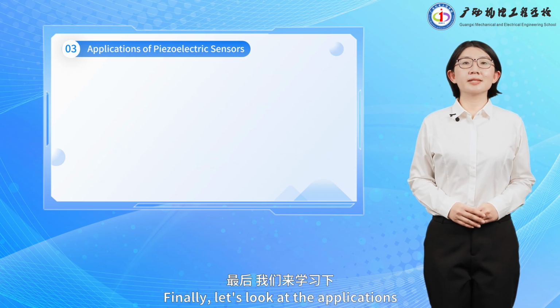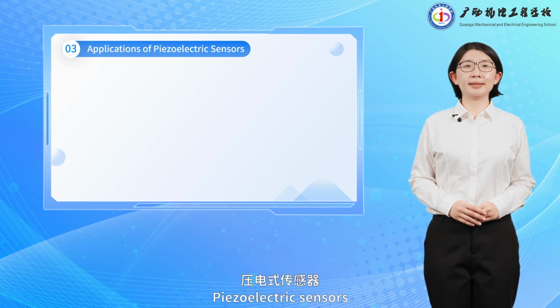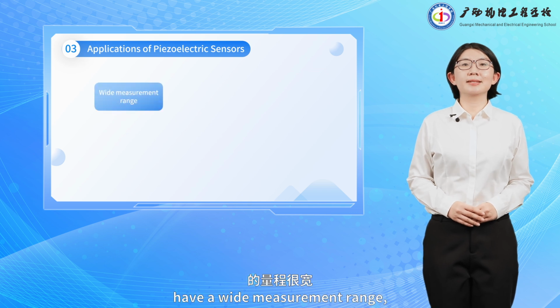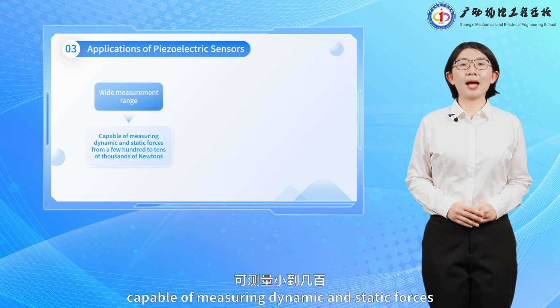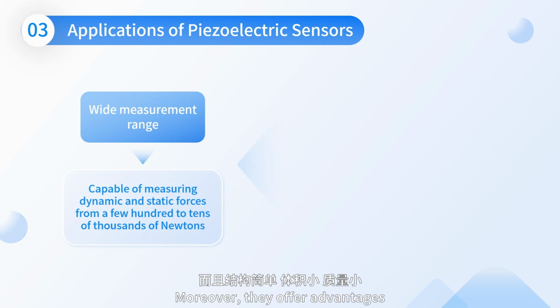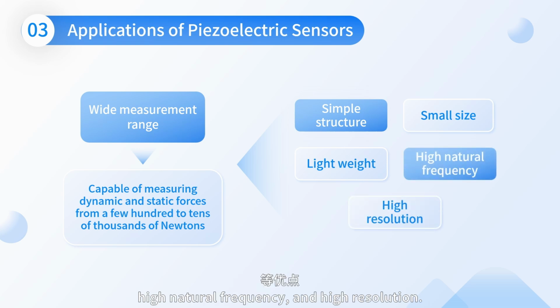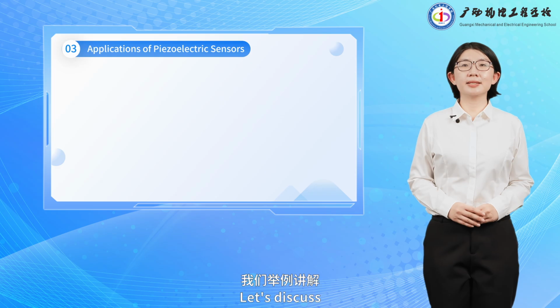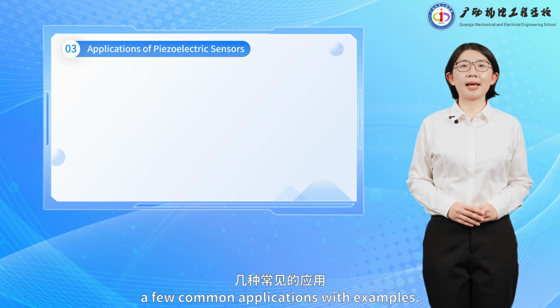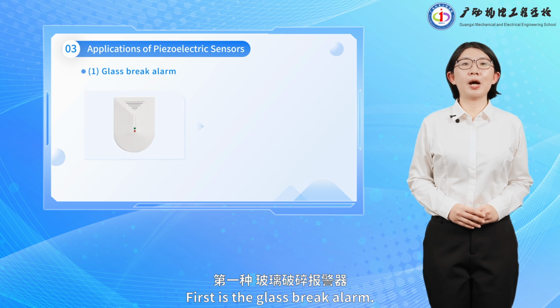Finally, let's look at the applications of piezoelectric sensors. Piezoelectric sensors have a wide measurement range, capable of measuring dynamic and static forces from a few hundred to tens of thousands of newtons. Moreover, they offer advantages such as simple structure, small size, light weight, high natural frequency, and high resolution. Let's discuss a few common applications with examples. First is the glass break alarm.